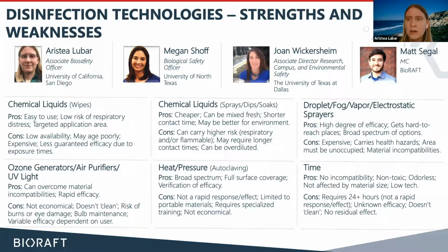If someone was known to be positive, we implemented a 24-hour hold. Since we have single pass airflow, with 8 air changes per hour, that gives us the time to make sure that if there are aerosols in the space, they have cleared out of that area. And anyone entering the spaces then has a decreased risk.